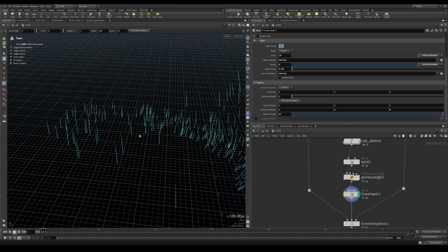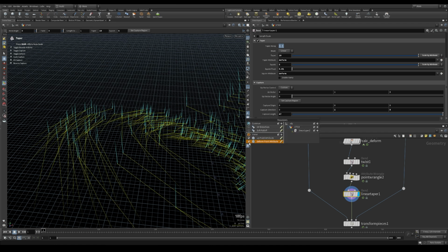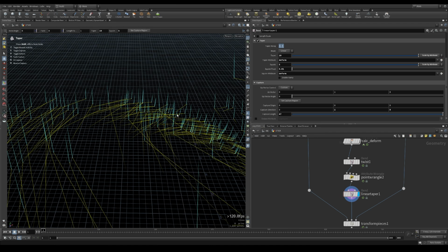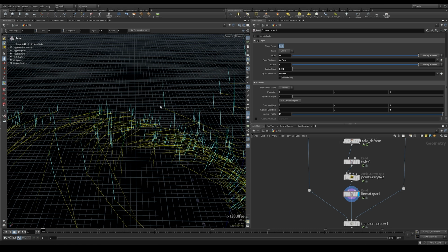With a quaternion, you can take a vector and say, rotate this vector by a quaternion. Inside the quaternion itself, you just need to define the angle of rotation, so how much you want to rotate the object, and on which axis. And we have both, because the angle will be a full 360 degrees, and the axis we want to rotate on is the up vector. So basically we just need to say to the points, rotate your normal using the up vector as a pivot point by a full 360 degrees.